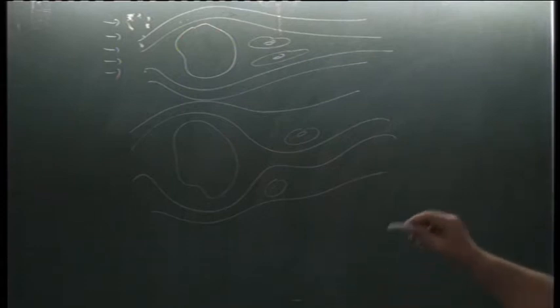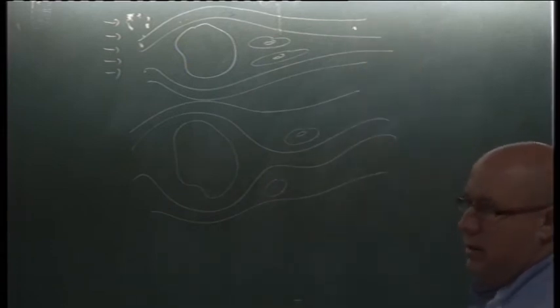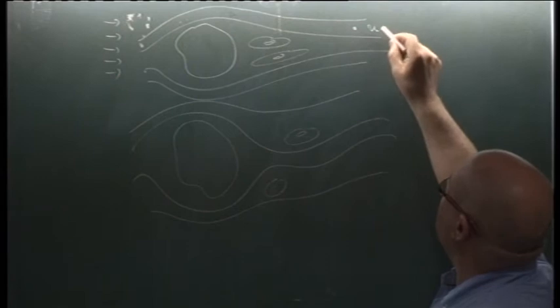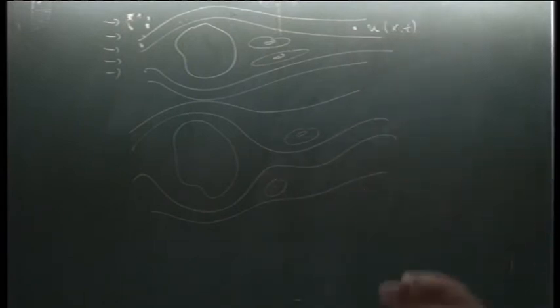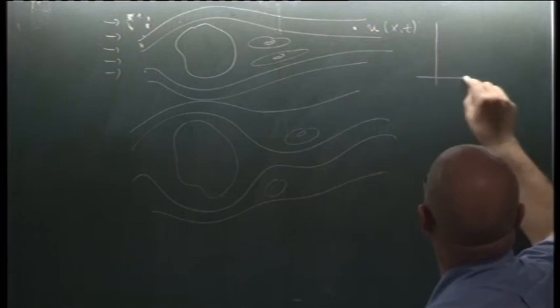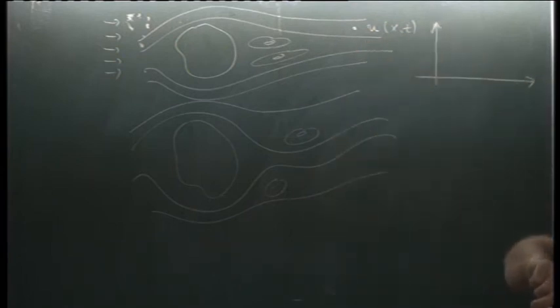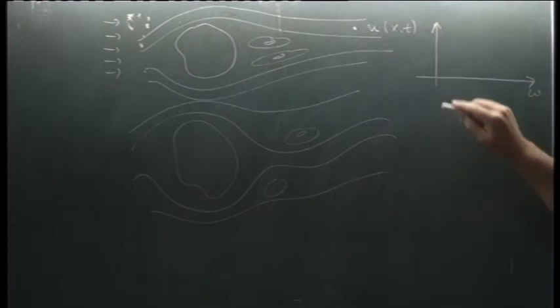Now, in that case, let's take a point, to understand the physics. And let's look at one of the variables at that point in time. I said the velocity, but it could be the pressure, the energy, whatever. Let's plot the spectrum here. That means we Fourier transform that signal, and we plot the frequency against amplitude.